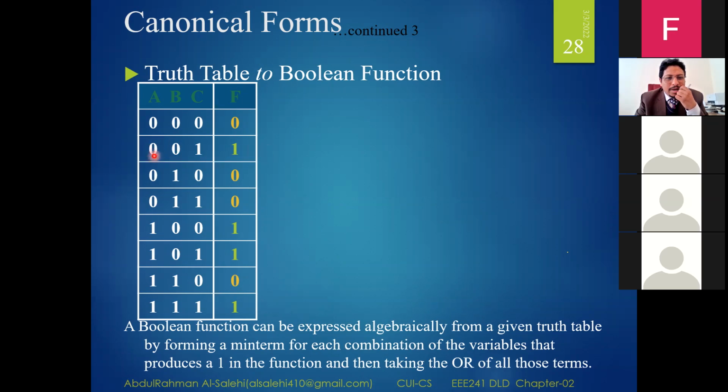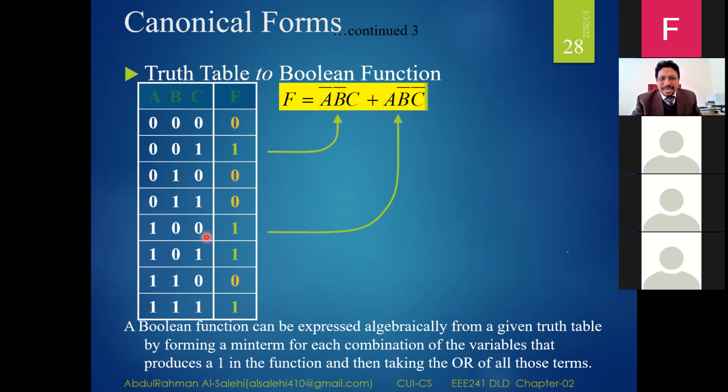How? I have to convert this to 1, because I'm using an ANDing gate, and this is already 1. So what will be the result here? It will be A prime, B prime, and C without any complement. The second one here, if I come to this one, this one is 1 0 0. So in this case, A is already 1, means no need to take the prime. I will take the primes of the 2 others and I will OR them.